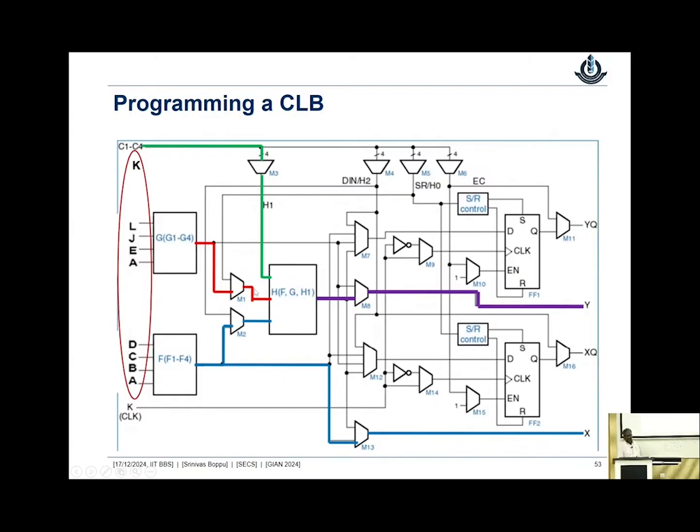So I got this P, which is nothing but AHL, and that is one variable now. Once it is implemented, it is one variable for me. I am representing AHL with a P, and now this final Y is a function of X, K and P. Again I have a 3 input lookup table, I am just giving them to it, and then it is implemented here. Okay, now this is what the synthesis tool does.